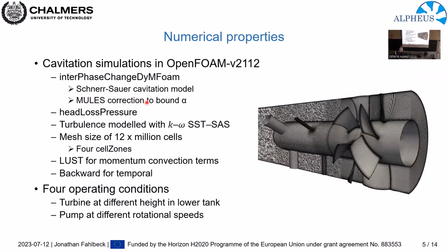And more interesting, how the cavitation simulations are carried out. I use OpenFOAM version 2112 together with the interPhaseChangeDyMFoam solver. In this solver, I use the Kunz cavitation model, which is basically a mixture fraction model. So you solve one set of the Navier-Stokes equations, you don't solve two separate Navier-Stokes equations. With this model, you basically track the volume fraction, which is denoted alpha here.